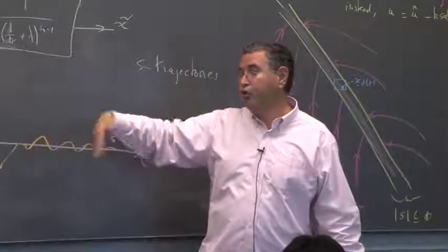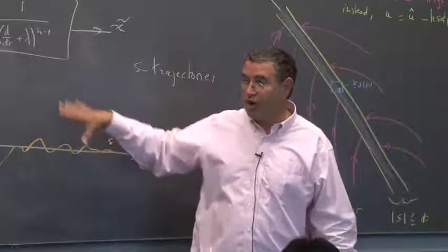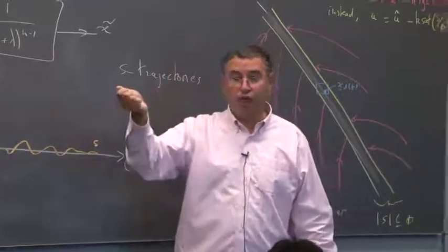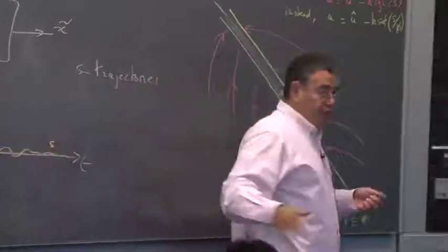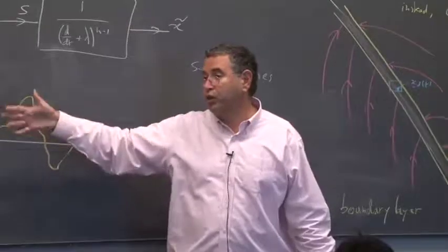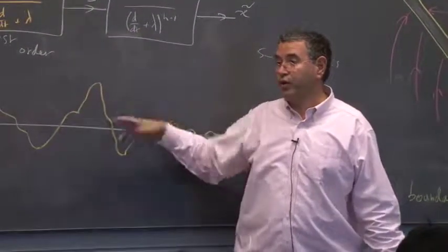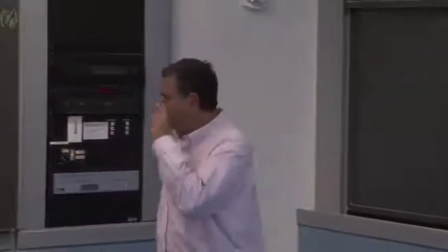Right? So whatever noise you have on x dot, x double dot, and so on, you'll see it in S. It will look much more noisy. You wouldn't see it on the most filtered version, which would be the tracking error. So if this gets really noisy, you figure out there's something wrong, or at least not done well enough with your sensors or with your observers or something like that. If this plot gets really noisy, which you wouldn't see in x tilde. Okay, so that's the first remark, if you want.